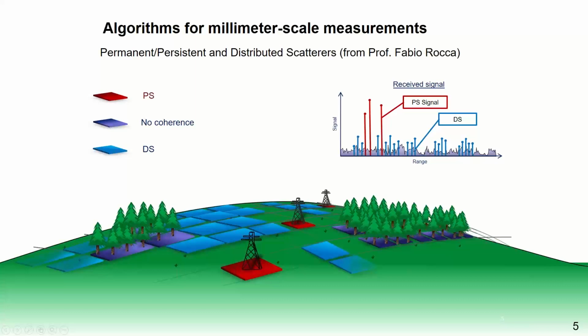Because of course we cannot measure the displacement in forest areas. We can do it in theory when we have very long wavelength, something like the P-band in the future from the mission Biomass, which will be launched in the next 2 years. But at the moment we cannot do that. So the approach to solve the problem of the atmospheric disturbance and rapid variation here is that we're not just using two images, but instead we use a very long time series of SAR images. It means that we use not just one, but many: 20, 50, 100, even 1,000 in future.